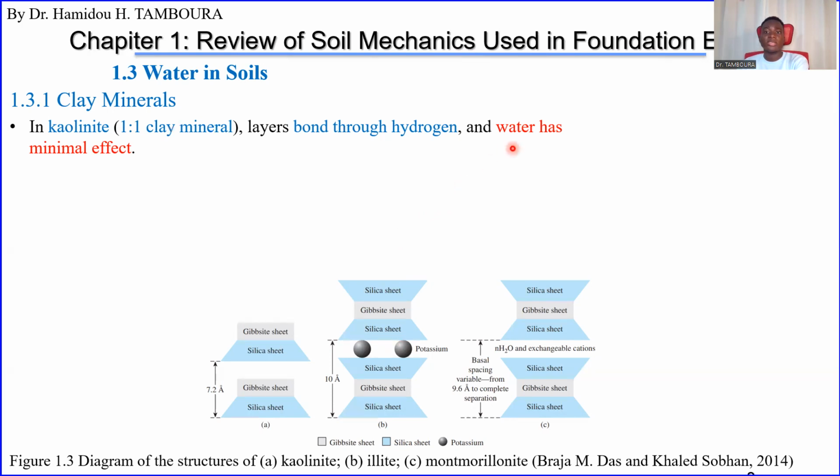What is important is how these clays behave when you add water to them. For kaolinite, the layers bond through hydrogen and water has minimal effect. So if you are doing a foundation and you have this type of clay, maybe you don't have to worry too much about water.